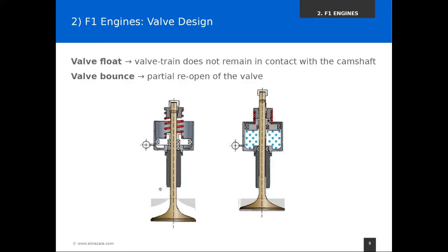So if we want to, for example, suck in new fresh gas fuel mixture, it has to go around the valve and then goes all the way through here, and then we have it in the combustion chamber. If we want to close the valve, here on the right is closed, then, as I said, this is not drawn entirely correctly, but this area basically closes, the valve touches the cylinder head, and then the gas cannot go outside.